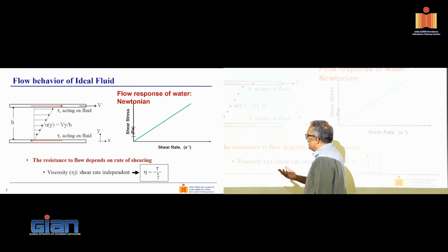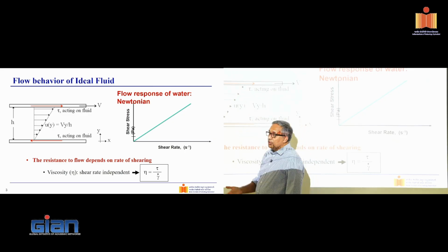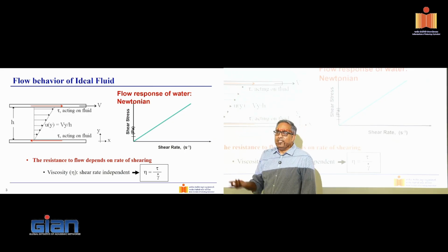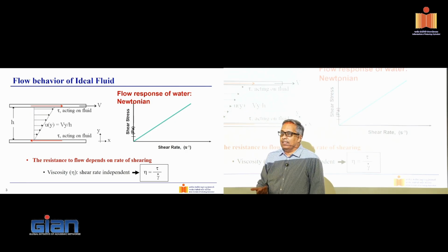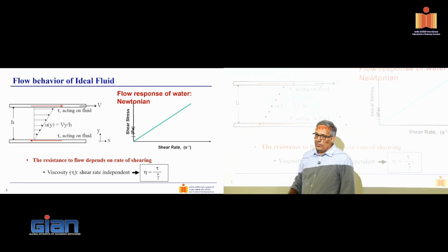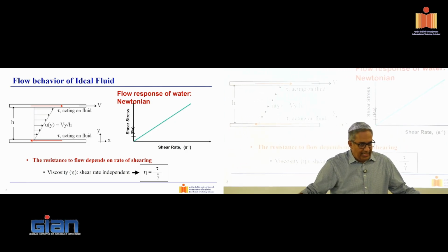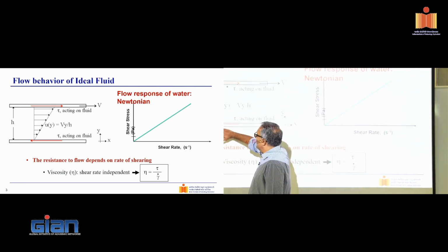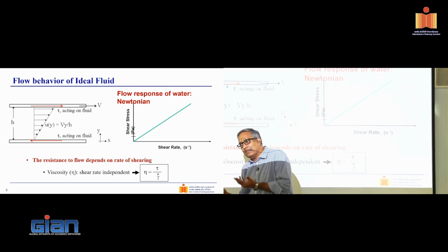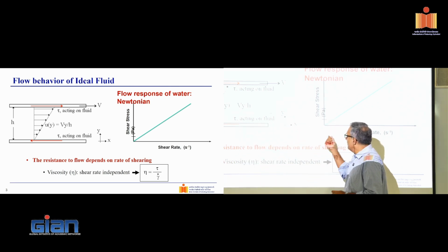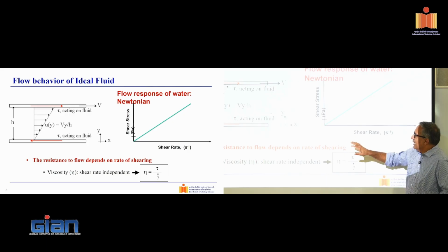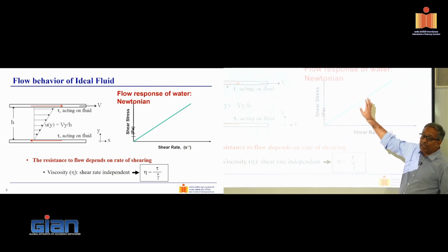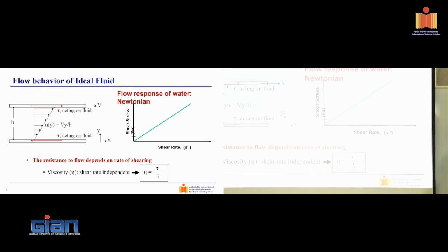Now, why do I say that? What if this velocity profile was not linear? Then everything changes, right? Under the assumption that I get a linear velocity profile, then I can say, well, this is my strain rate, okay? And this is the resistance I get, assuming that the stress is uniform or fitting some theory to it. I come up with this theory, which is basically, we define a material called a Newtonian fluid, where we say that the resistance is directly proportional to the strain rate.